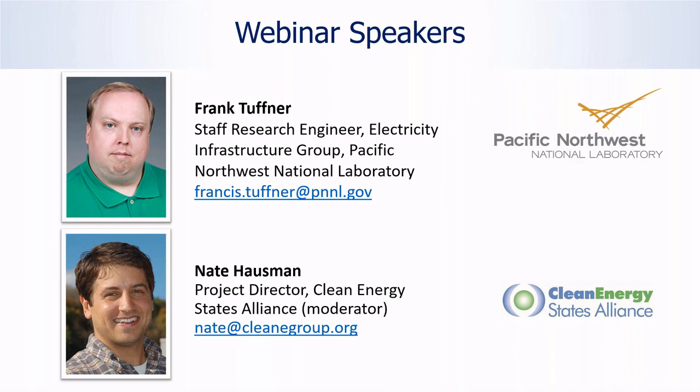It's a government-run data repository. They have a lot of information on typical home construction, typical fuel consumption, appliance use, things like that up on their website. The other option is sometimes you can use complementary software. Like if folks are familiar with EnergyPlus, it's a very detailed building energy simulator. You can use that to extract information and then turn around and use that to populate the GridLABD model. But there are conversion scripts.